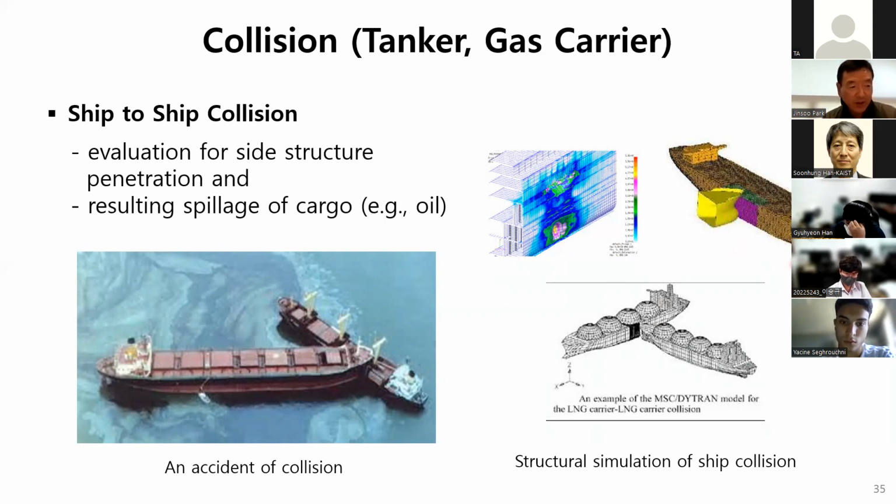This figure shows finite element analysis models of a large oil tanker and LNG carrier. In this analysis, very large displacement nonlinearity evaluation and plate ruptures are included to analyze collision penetration.